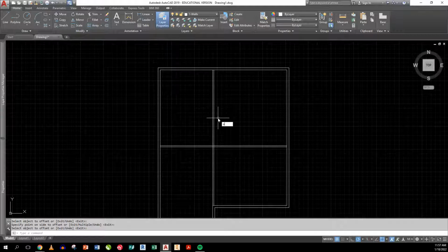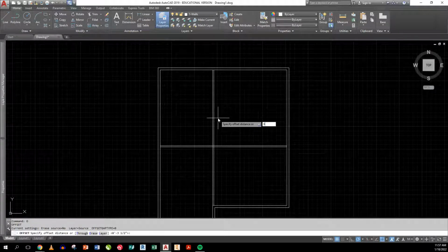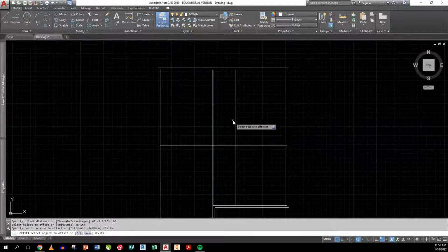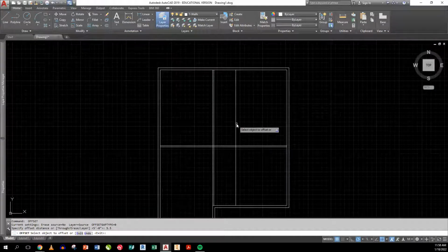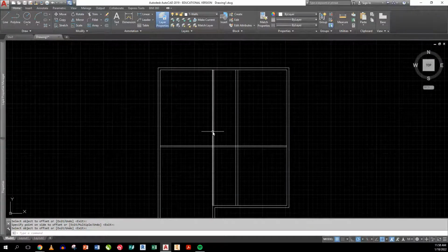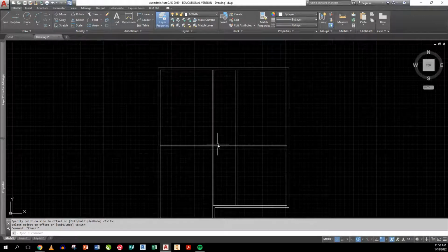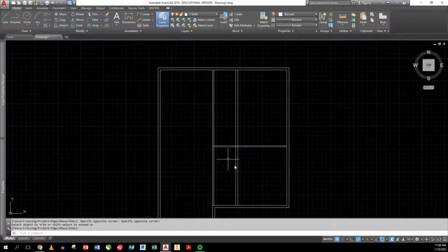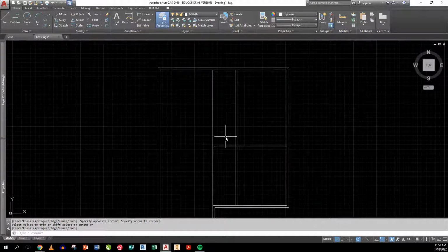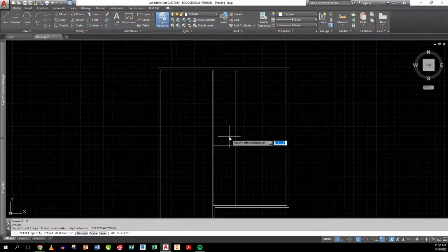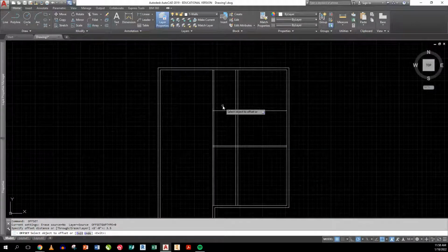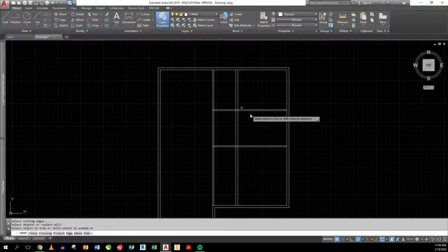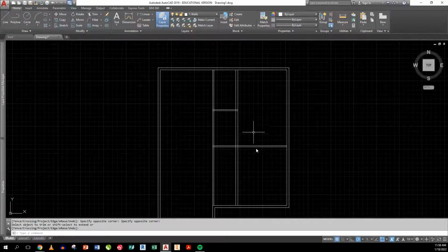Now, other things we've got to figure out. Okay, we know that basically 5 feet across is this bathroom closet area here. It's bathroom here, closet here, and that has to have a plumbing wall right here, which is 5.5 feet. Okay, we also know that no walls extend through like there. There's not a straight line across that, okay? So I'm just going to trim that off. I can know right now that if I offset the 8 feet, 96 inches again, if I want to type in 96, and then go 3.5, there we go. I'm just extending and trimming things off.